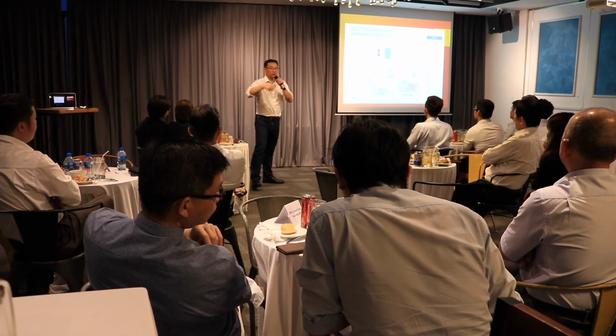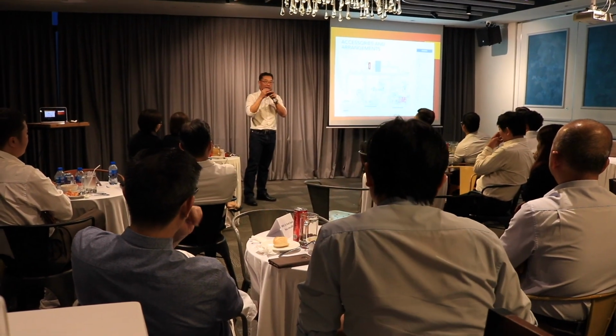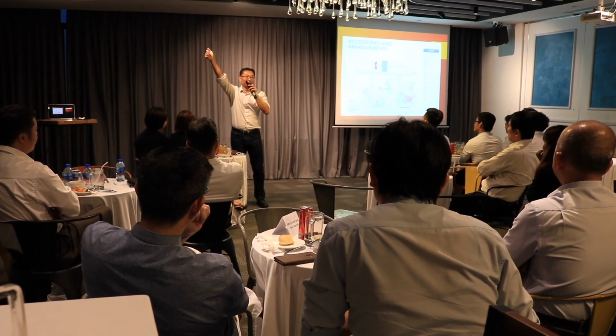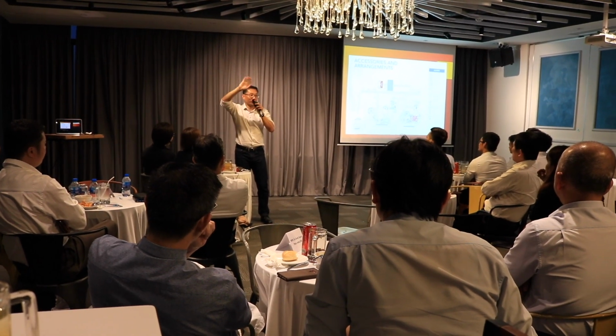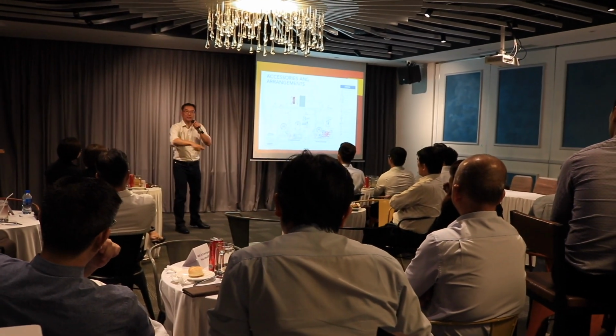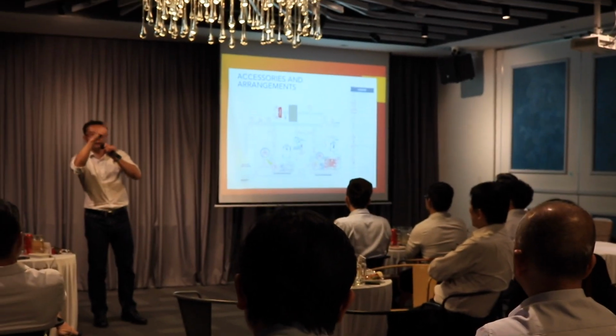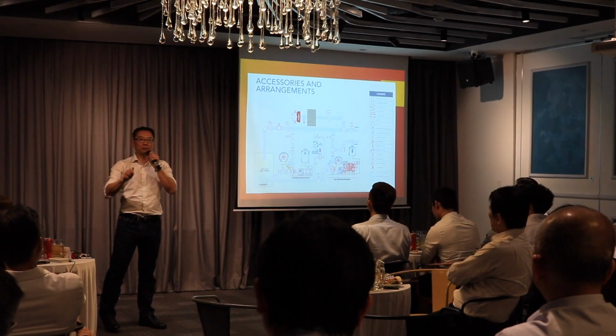Okay, the flow meter is checked weekly. For a fire pump, there's no such thing as: hey, I want to test, how should I test? Take a lighter, go to the sprinkler and activate the sprinkler. No. There's a flow meter here. So it's just a bypass. You lock the rest and then you bypass. You check the flow. Okay, flow enough, pressure enough. Okay, the pump system is good.